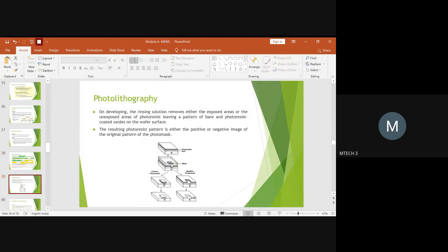Because here you'll be having the pattern which has been applied, right? So when you apply ultraviolet radiation, this pattern will be deposited on the thin film which has been developed. And this is by the photoresist phenomena. Okay, so it could be either due to positive photoresist or it will be due to negative photoresist. If it is of positive photoresist, the required pattern will be retained here. If it is negative photoresist, the required pattern is etched out and the remaining part of the material is retained.